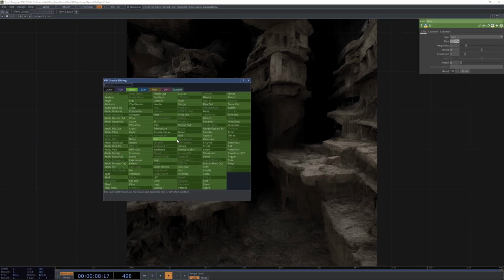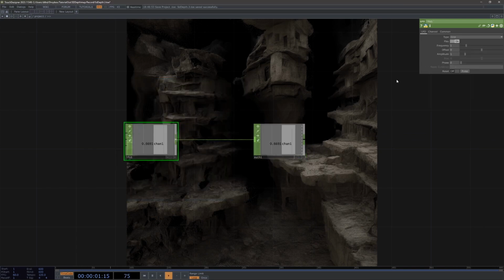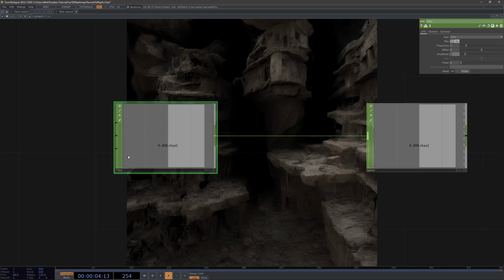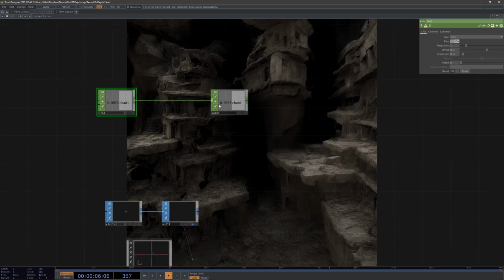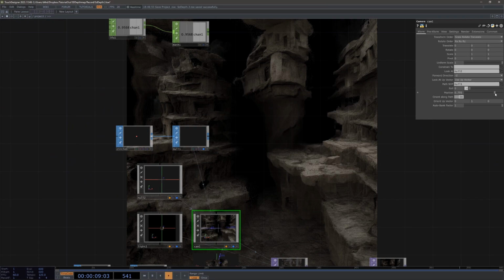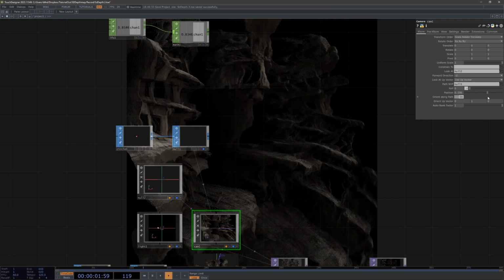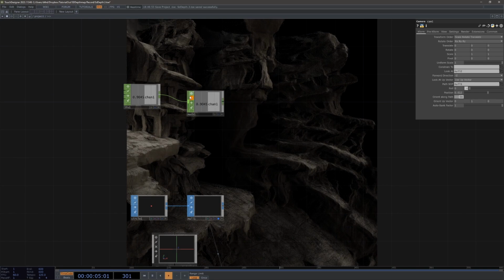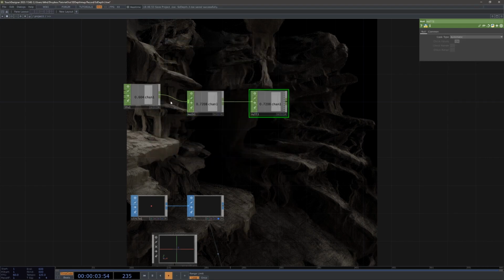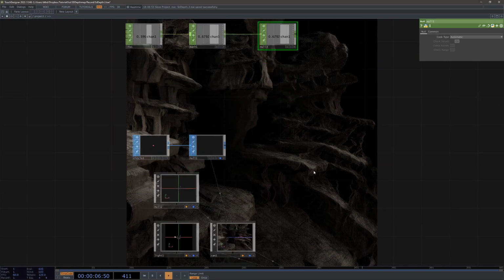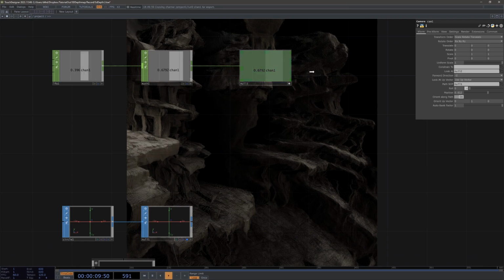And after this, a math. And this LFO, right now it's going from -1 to 1, I want it to go from 0 to 1, so I'm going to do an amplitude of 0.5 and offset of 0.5, and now it's going from 0 to 1. And in this math we say it's from 0.6 to 0.8, adding a null. Of course, for your project, you do what you want with the amplitude.